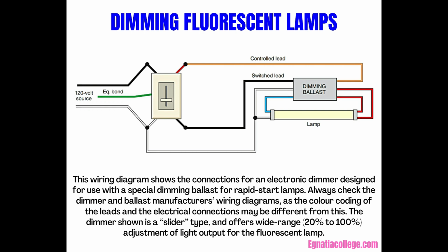Without special dimming fluorescent ballasts and controls, a simple way to have two light levels is to use 4-lamp fluorescent luminaires. Then, control the ballast that supplies the center 2 lamps with one wall switch, and control the ballast that supplies the outer 2 lamps with a second wall switch. This is sometimes referred to as an inboard/outboard connection.